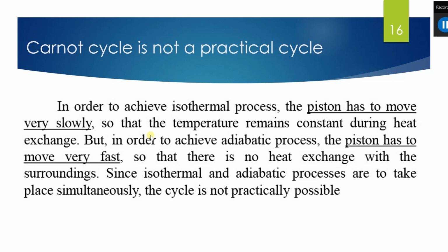We already said that a reversible cycle is not a practical cycle, and also a Carnot cycle is not a practical cycle. This is because in order to achieve the isothermal process in this Carnot cycle, the piston has to move very slowly, so that the temperature remains constant during each heat exchange.